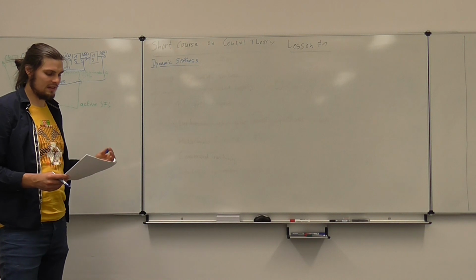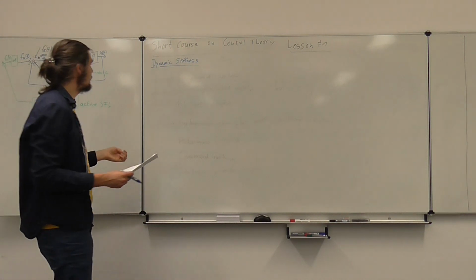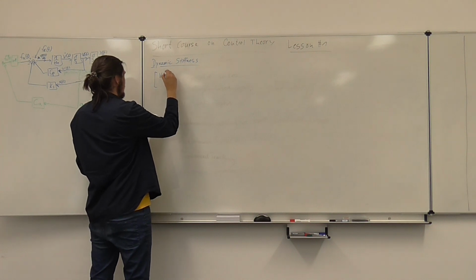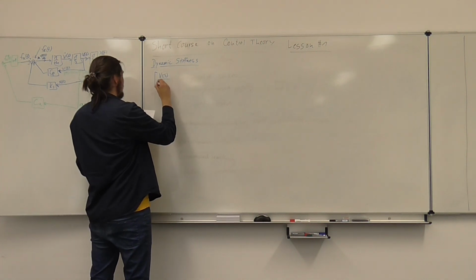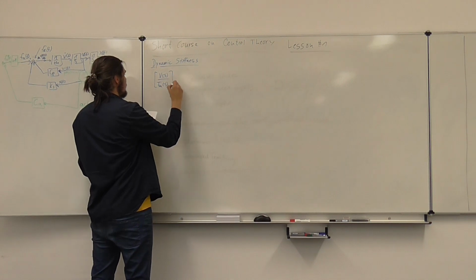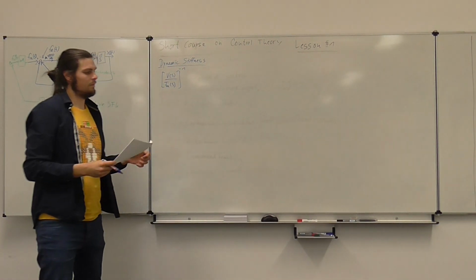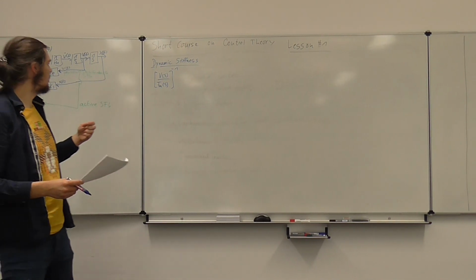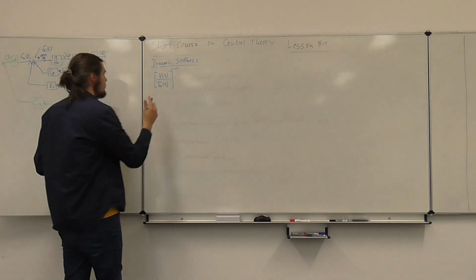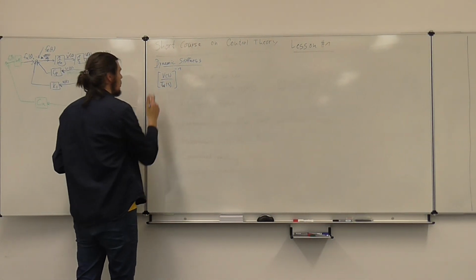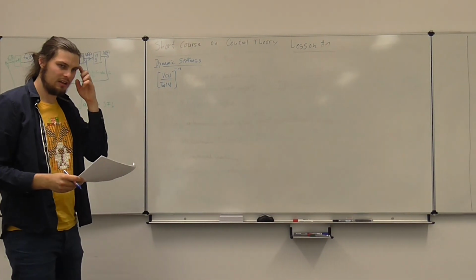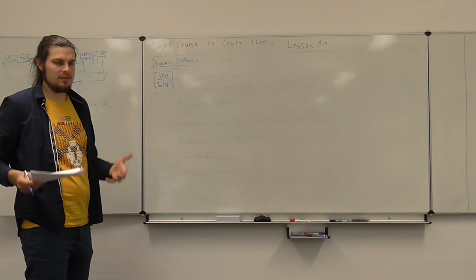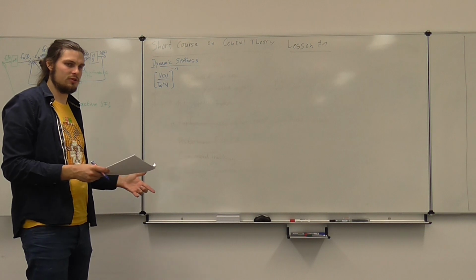So it's basically the state in this case, Es over Fd of s, the inverse of it. So this tells us how many units of disturbance I need to change 1 unit of our state. Or in other words, it tells us how stiff is our system in regards to our disturbance.